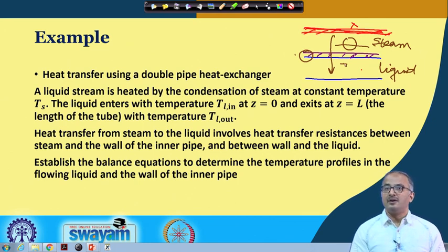On the other hand, for any kind of solid, there is no contribution of convective heat transfer. So it is only the conductive heat transfer, and as I have just said we are neglecting the radiative contribution. For the conductive heat transfer to be appreciable, we have to have a high thermal conductivity of the solid.